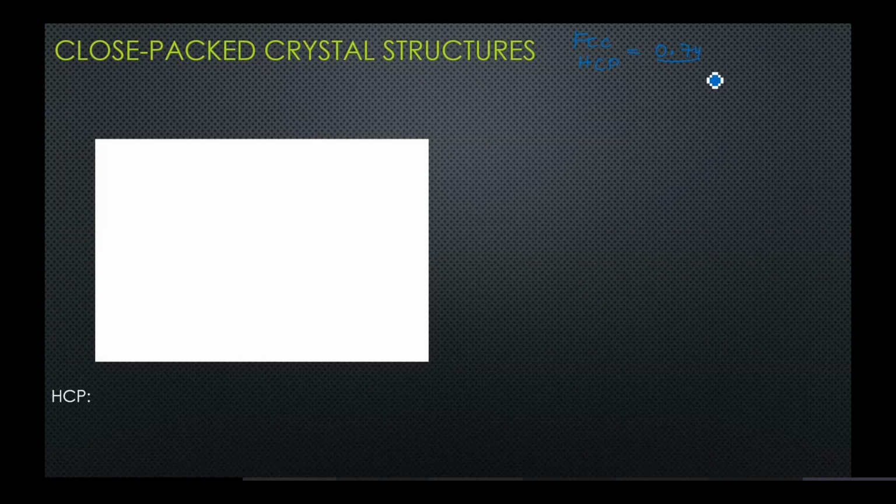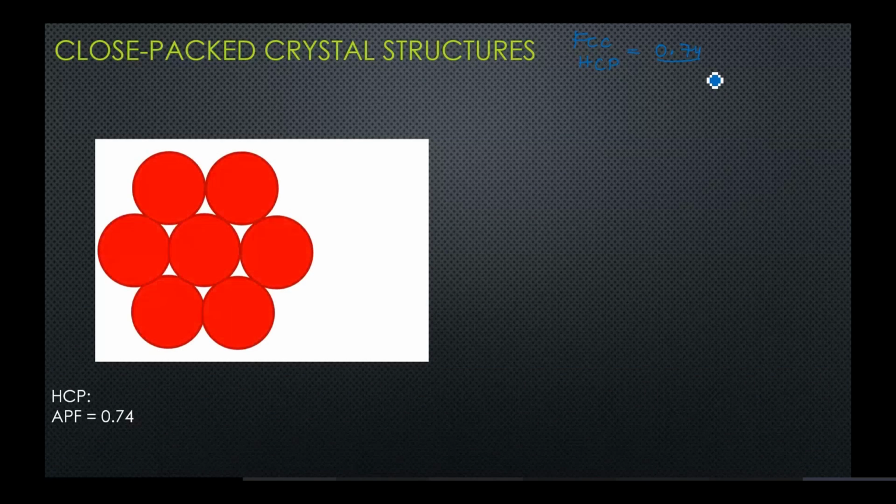So let's say in an HCP, the basal plane is closely packed. This is the closest they can get packed in an HCP crystal structure. As I'd already mentioned, there are two sort of cavities, one which is facing upwards, the other which is facing downwards. The second layer in an HCP would either occupy the upward cavity or the lower cavity.